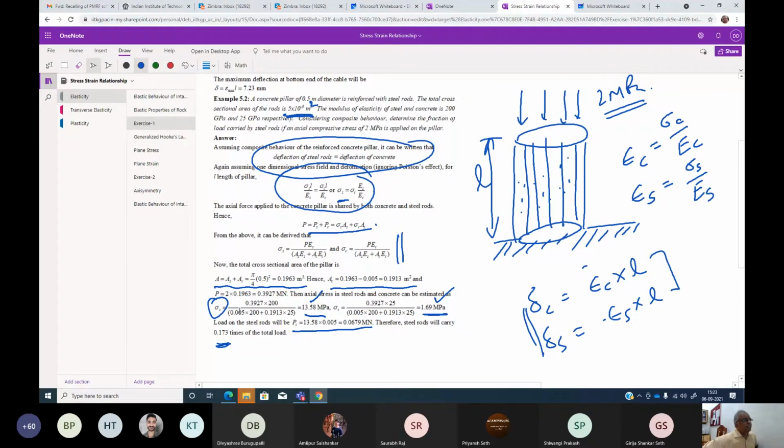There is another reason: if there is any lateral movement, let's say an earthquake, the rod also protects, because concrete will give you zero protection in earthquake type of loading, meaning dynamic loading. The rod will help you there. In compression, it takes the majority load. In tension, it protects you from complete collapse.